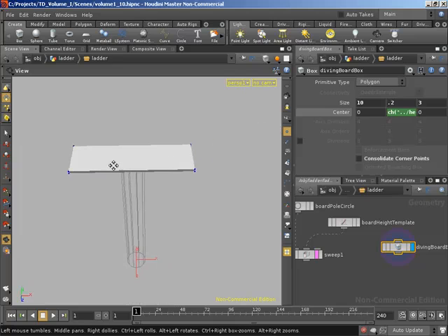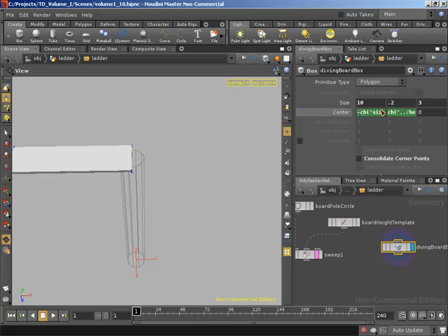So center X is going to be slightly interesting, so let's do this in stages. I want to offset in the negative X direction. I just want this to be the diving part of the pole. That's just an arbitrary choice. So I'm going to offset by our size in X divided by 2, and that's going to push us over so we're centered up on the pole. I'm then going to come back based on the pole radius.